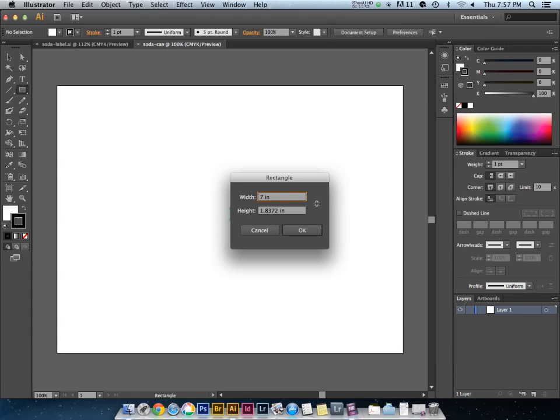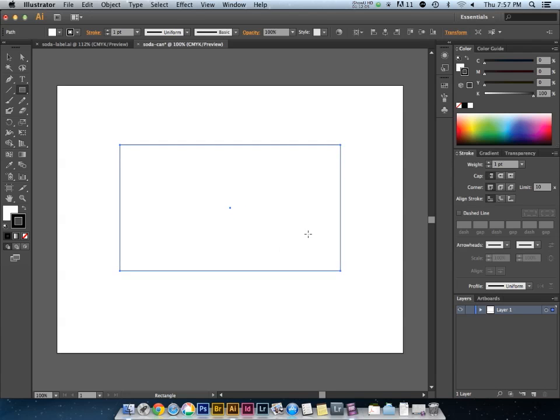That will still give you 7 inches, even if you're displaying points or picas. That's fine. And then I'll move over to the height field, type in 4, and I can type in inches, and I will have a box that's sized to that dimension.